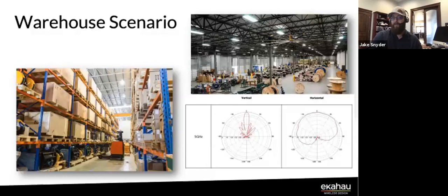When I say it's 3 dB from peak, that really means 3 dB, which is often what you would see from an integrated antenna AP. Well, at 60 degrees, I'm back to where I would have been if I'd used an integrated antenna AP. So it doesn't just stop at that mark. It just means that's where I get that 60 degrees from.